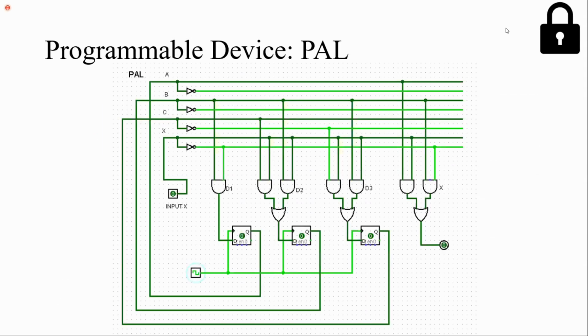So same circuit, but I did it on Logisim, and I'll show you it actually working in a bit. I still use the same D flip-flops. The input X is just the input that the user puts in, so a random sequence, and I map it through with the clock cycle. And when it's detected, then X goes high.